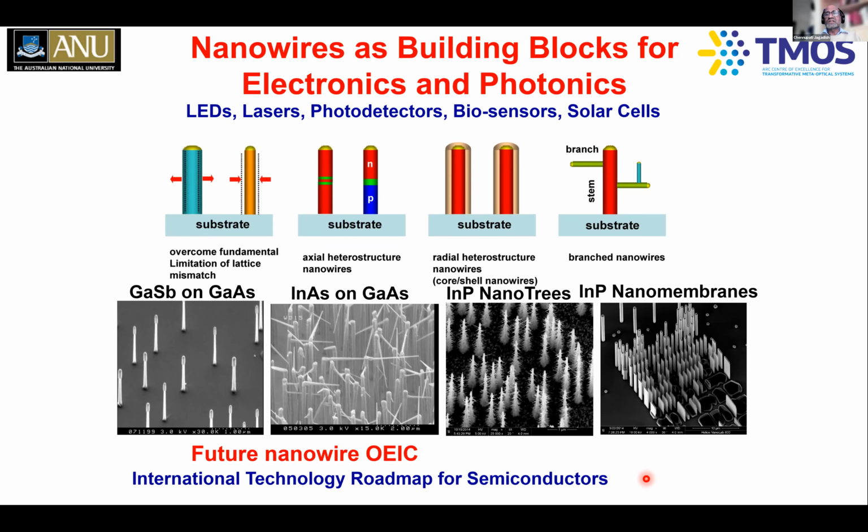Instead of having transistors in the lateral direction, you can have transistors in the vertical direction so that you'll be able to pack more transistors. But also these III-V semiconductors, not only are they direct band gap semiconductors, they also have a higher carrier mobility. That means faster transistors. III-V semiconductors are better, but the lattice mismatch has been limiting us; now lattice mismatch is no longer an issue. In fact, we are able to make III-V nanowires on silicon. Recently IBM has demonstrated indium gallium arsenide nanowire transistors on 6-inch wafers of silicon, showing excellent performance, indicating that the future is looking very bright, both for electronics and photonics, for example.